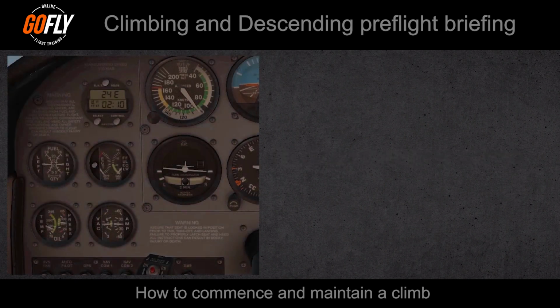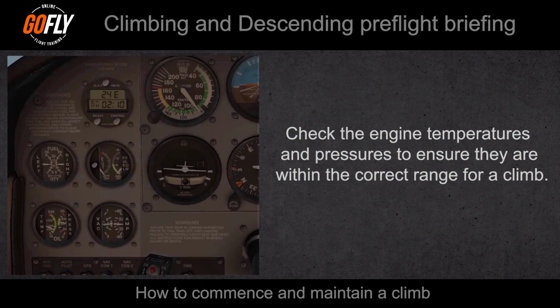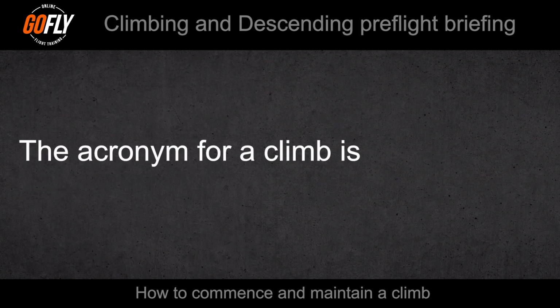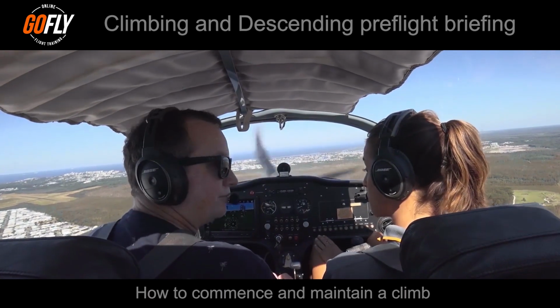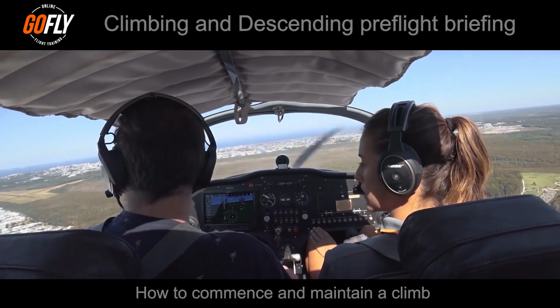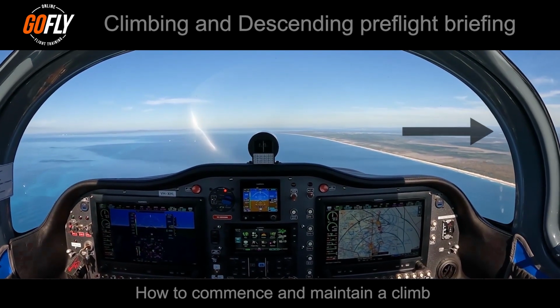Before commencing a climb, it is important to check the engine temperatures and pressures to ensure we can increase the engine power without harming the engine. The acronym for a climb is LPAT, which stands for L for lookout. Before commencing a climb, the pilot needs to have a very good lookout for other aircraft. The best way to scan and look out is to look left, center and above, and right.